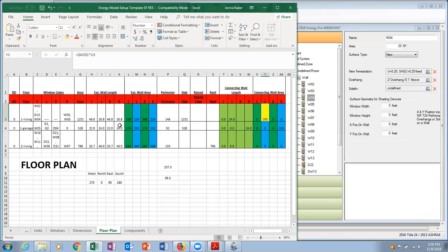So it looks like I didn't do this calculation before, but I need to do it now. So from the exterior wall area on that left wall, since it's not the whole wall open to the outside, it's not all an exterior wall, we're going to go ahead and subtract this connected wall area.